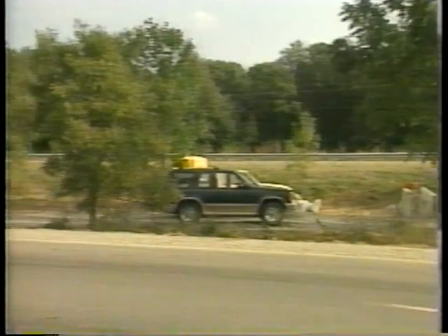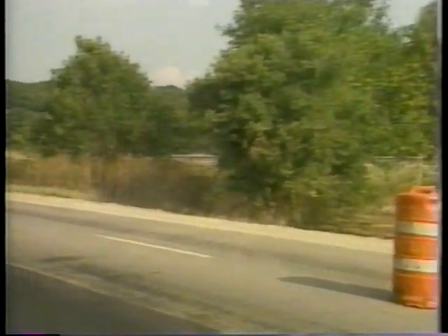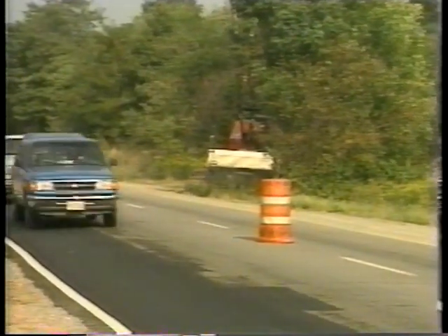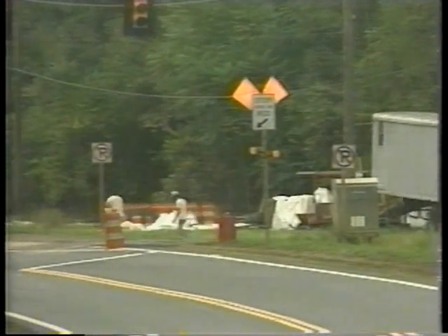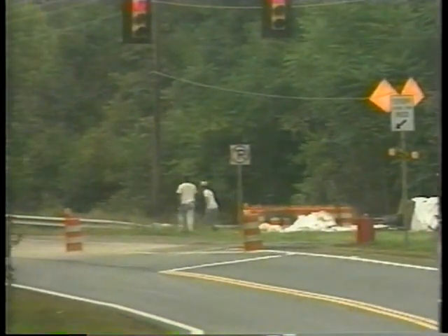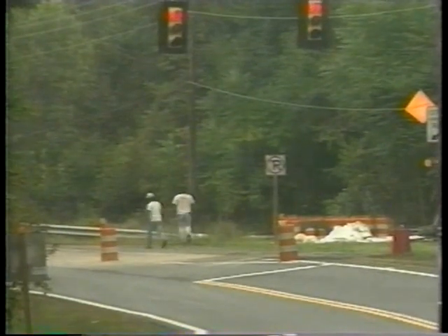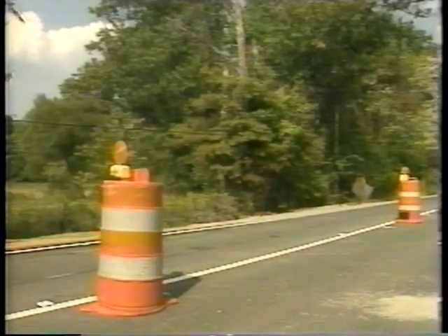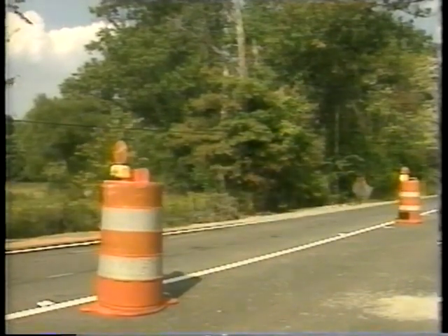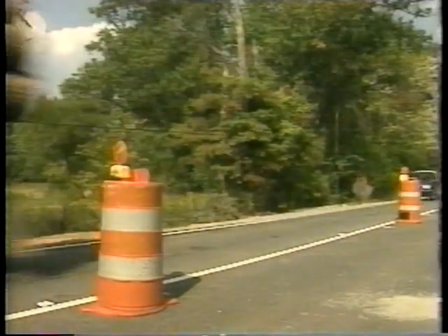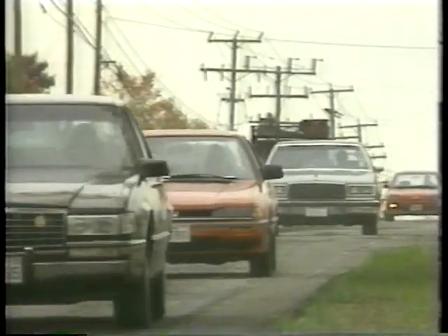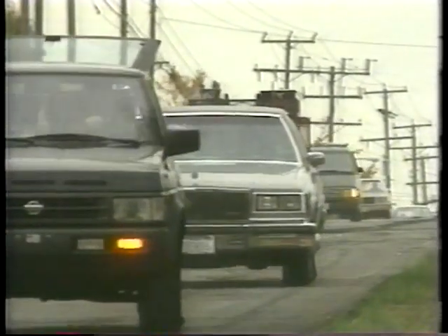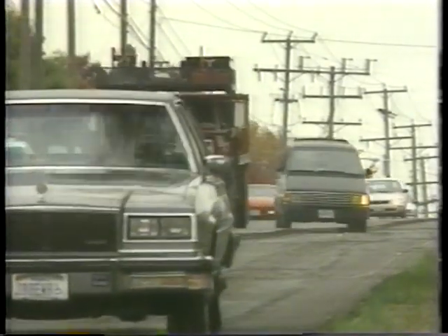Storing equipment and materials outside the buffer area, the area which an errant vehicle may need to return safely to the traveled lane. Providing workers safe access to work and storage sites within the work area. Designing detours and crossovers for a speed no less than 15 kilometers per hour below the speed limit of the approach roadway.